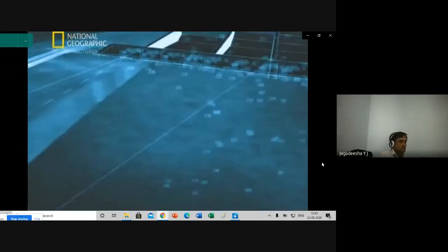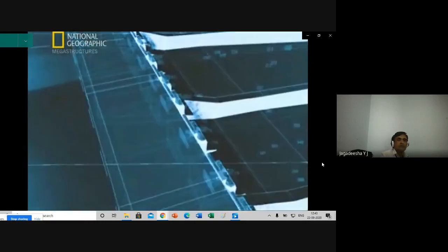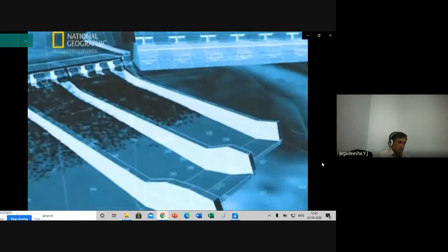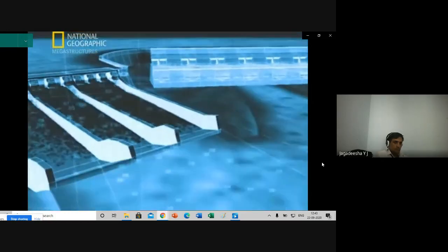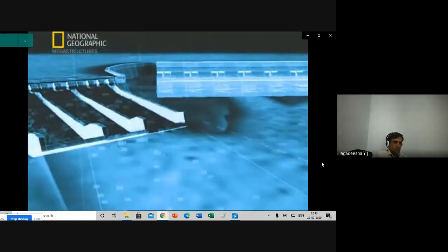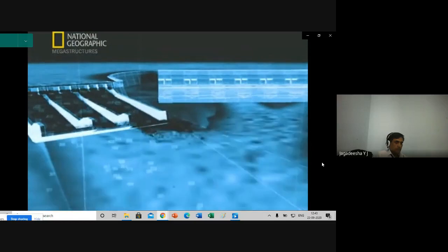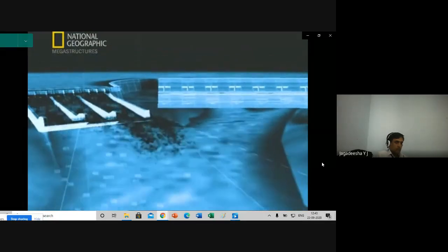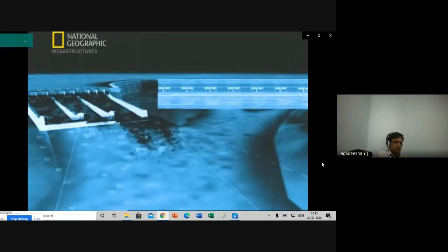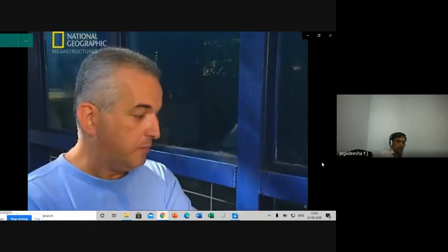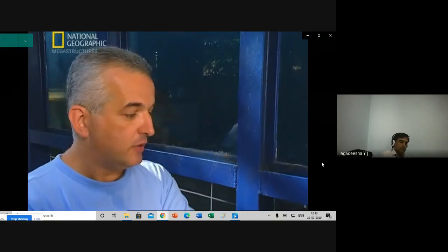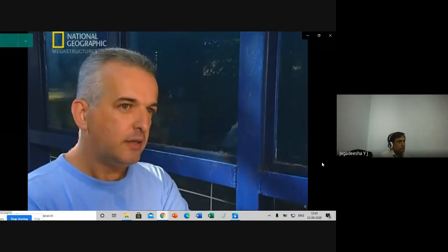When water crashes off the end of the spillway, it lands below the dam with great force, churning up the river. This energy must be dissipated using an upward curve like a ski jump that forces the water up into the air, reducing its force. "The energy dissipation is so important that you could say a good design of spillway can avoid damage to both the actual structure and the land downstream."